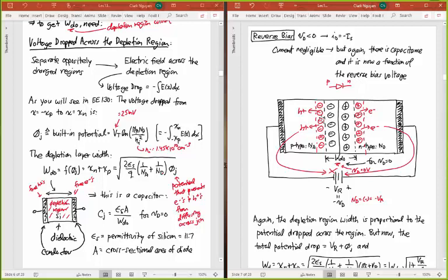But the end effect is you're creating more of this static charge, negative on this side, positive on that side, which means effectively your depletion region has gotten bigger. So I'm now going to call this WD instead of WD naught, because it's not the zero bias WD. It's basically a depletion region that's gotten bigger. And so if I wanted to think of this in terms of that capacitor that I showed before on this side, so focus on this thing right here on the left side where I'm circling, I'm going to draw little versions of that on the right side.